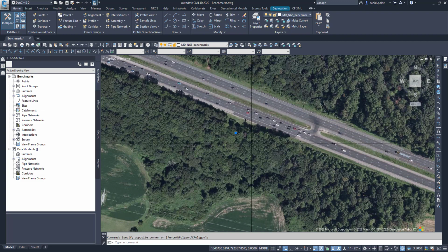If you can find a location where you actually have a GPS point that you're doing your survey, it's highly recommended that you use your survey elevation based off of that, because that is a known point elevation. And then that way you can take your surveyed points and align them to this specific elevation and adjust your elevation of your survey points to this elevation that is known.